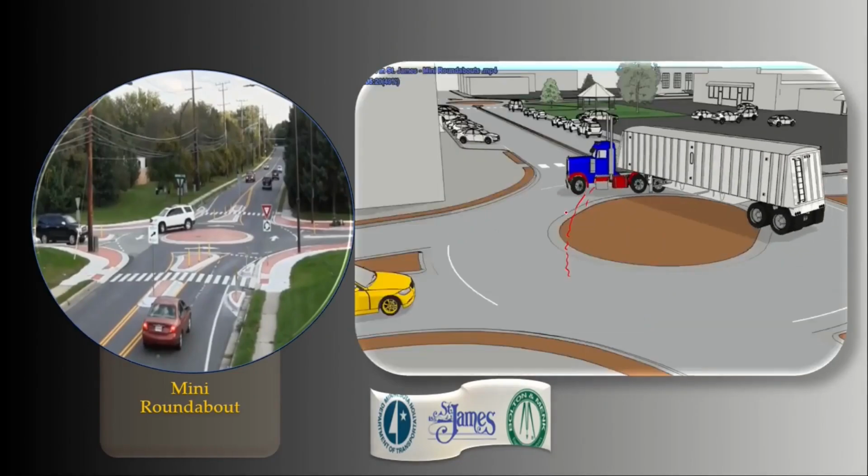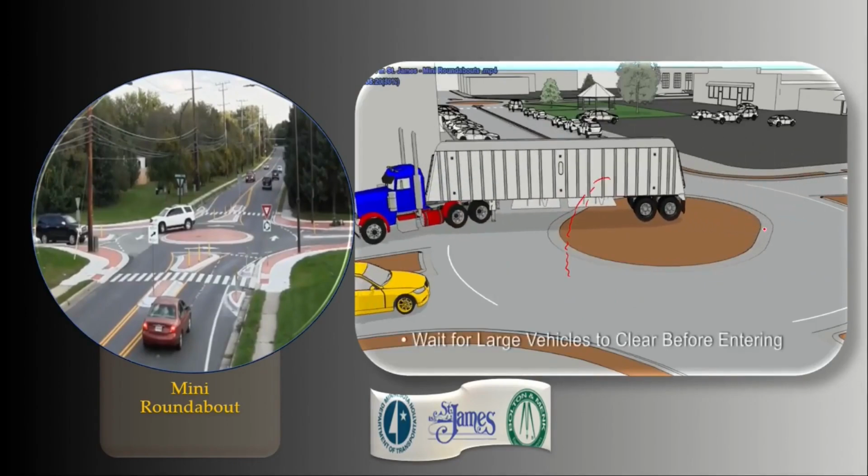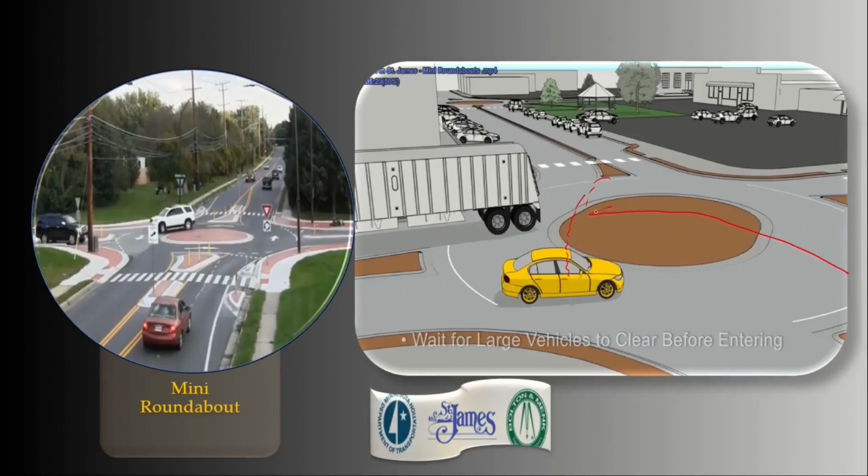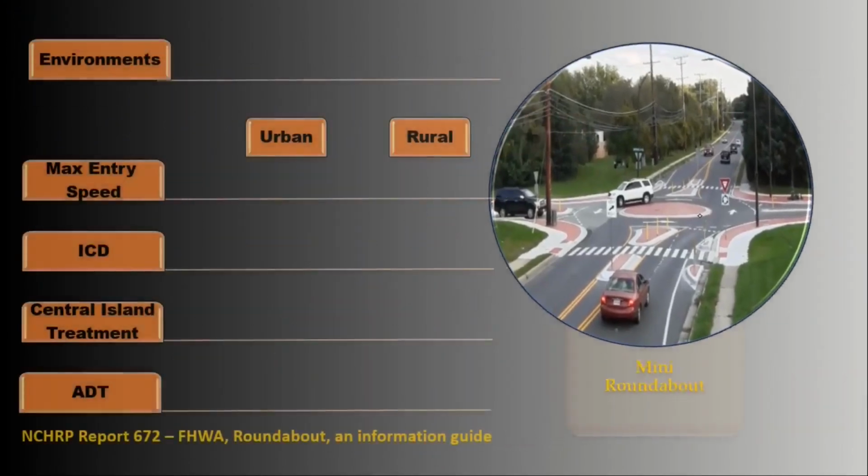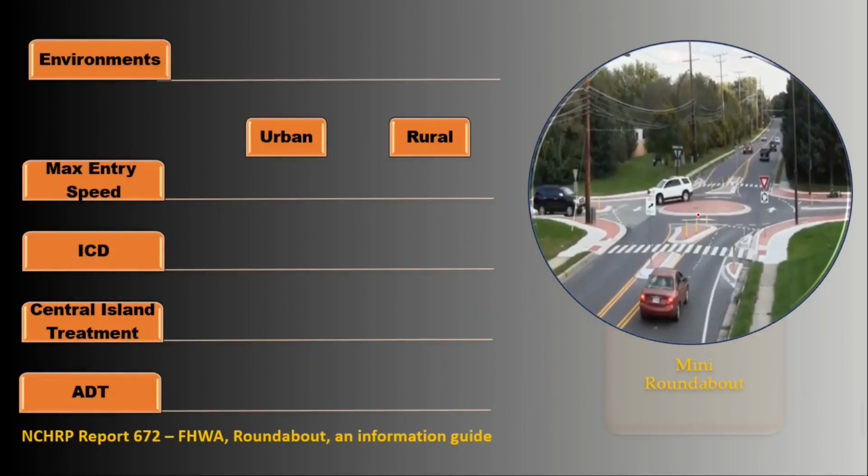Depending on the size of the mini roundabout, it may even make its left turn completely over the center island. Some of the most important criteria that should be considered in designing mini roundabouts are the environment around the roundabout, maximum allowable entry speed, the size of the inscribed circle diameter, and considerations related to center island treatments and ADT.